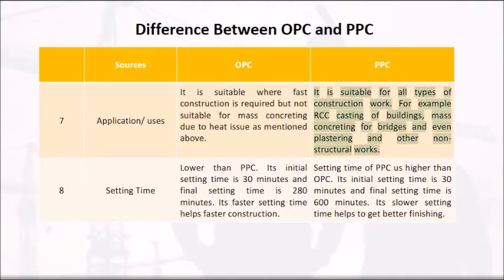PPC is suitable for all types of construction work, for example RCC casting of buildings, mass concreting for bridges, and even plastering and other non-structural works.